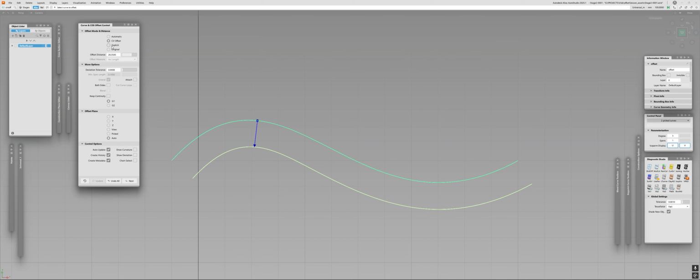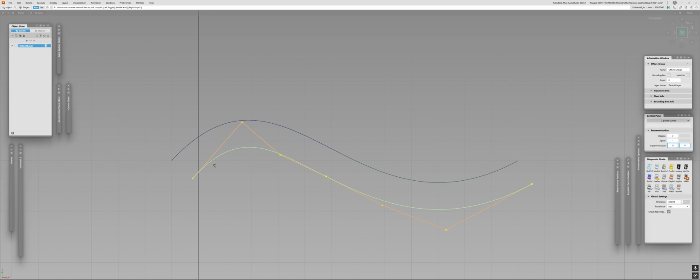But then there is an option in explicit. Instead of Alias taking the complexity of the curve on itself and calculating it based on its tolerance, the deviation tolerance and a lot of other stuff, here it gives you an ability to define what you want. How many of them do you want, right? And you may say, well, I want to have 3 degrees single span. Well, Alias will use the automatic approach, populate, move, reconstruct, not the CVs, but the actual points, and then give you this curve. Like, yeah, here, eat it.